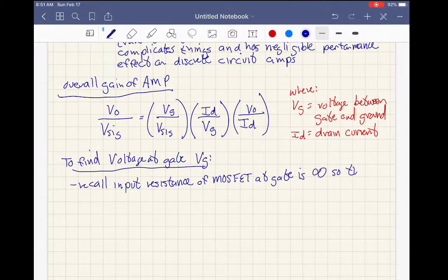So the amplifier input resistance at the gate is basically a function of the components: the source resistance, the gate resistance RG, which is a combination of RG1 in parallel with RG2, and the capacitance. I'll write this stuff down. So, amp input resistance.